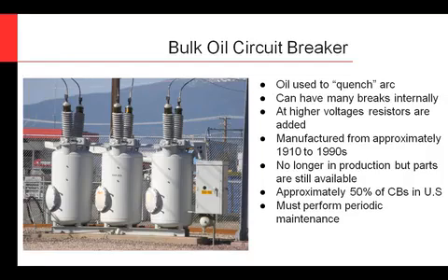These things have been around a very long time, and I'm sure everyone has seen these in the field. Approximately about 50% of them are still out there. They were manufactured from early 1900s all the way up until about the 1990s. So they're no longer in production, but you can still get a lot of parts for them. You can still maintain them. And that's one nice thing is you can maintain these circuit breakers and keep them running, but they do require a lot of maintenance. So generally a lot of people are pulling these out when they come up for maintenance and replacing them with an SF6 style circuit breaker.